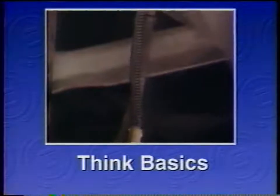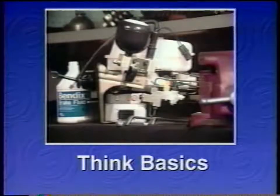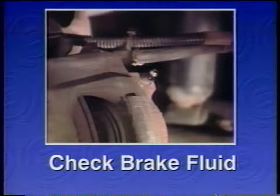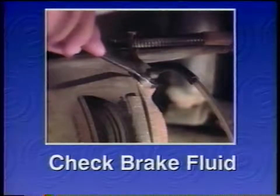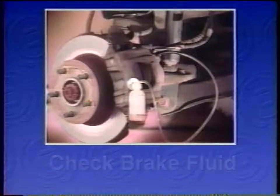So think basics and give the vehicle a quick visual inspection and correct any obvious defects. Check brake fluid levels. If low, add DOT 3 fluid to the proper level. If contaminated, replace with new DOT 3 fluid. Never use silicon-based fluids in anti-lock systems.